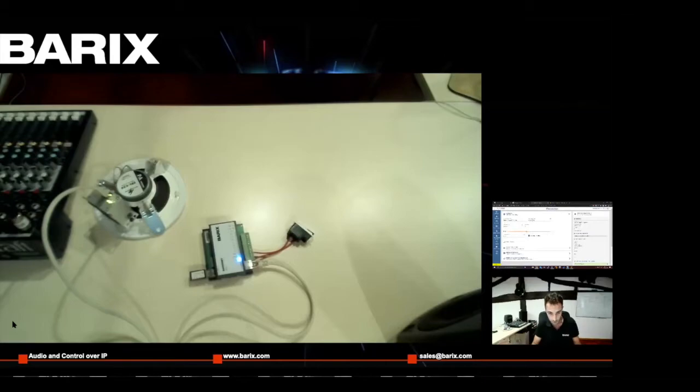This is the notification type. I have to select, of course, my triggers. I already selected here the general purpose input 1 from the Barionet device, but I can also select other triggers if I want to. In this case, I have up to 4 because the device has 4 digital inputs. The message details is nothing but the audio file that you selected to be played.